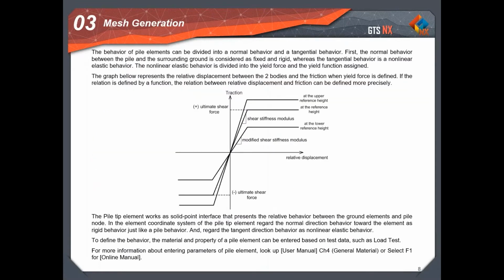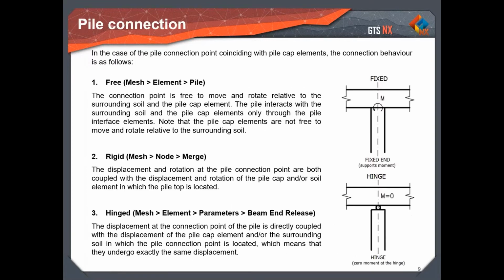Okay, to save my energy to proceed to the analysis step, I will just show you the behavior of pile elements like this. And this is about pile connection. Normally we use the fixed condition for the pile cap or single pile to ground. And I will share this presentation file as well after today's webinar session.